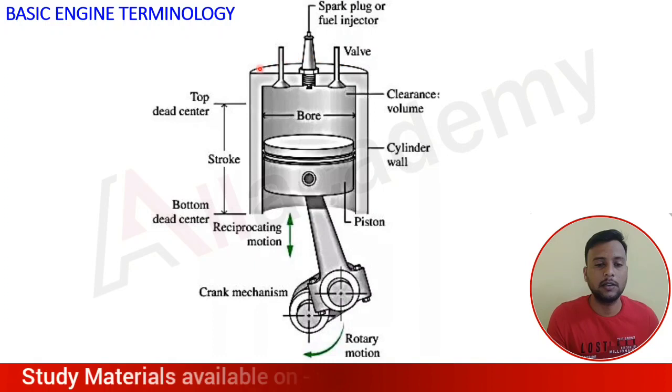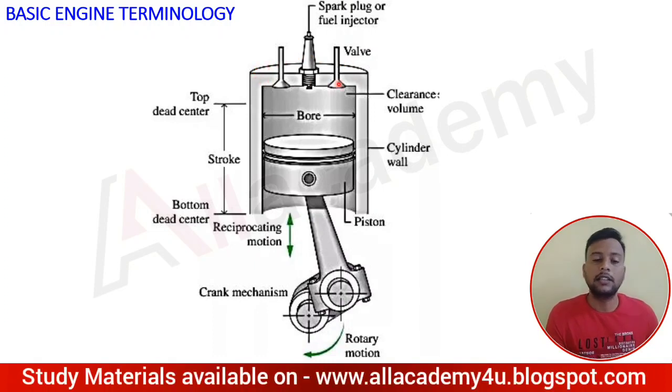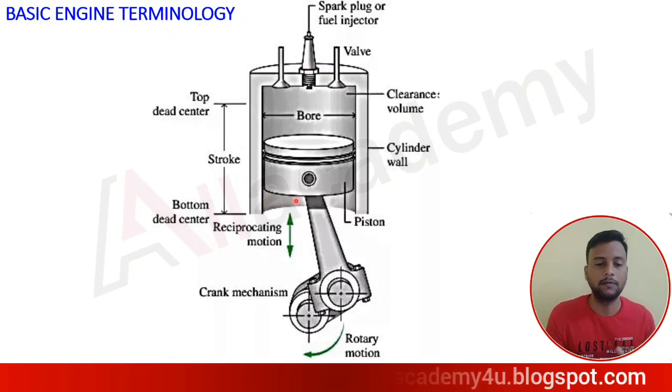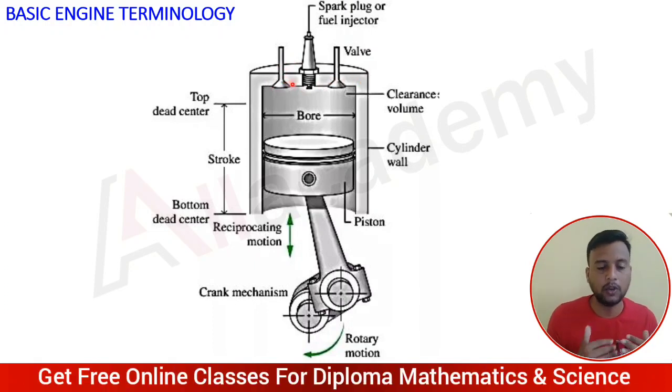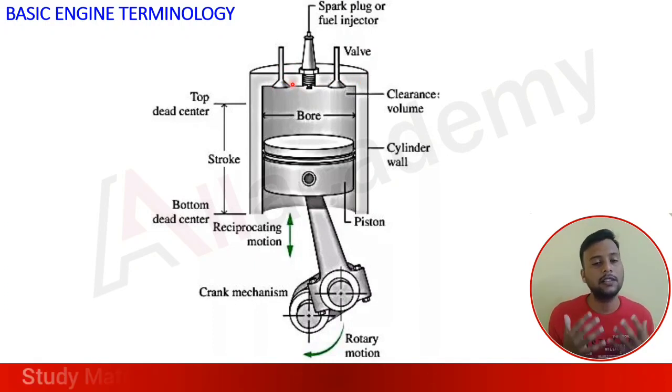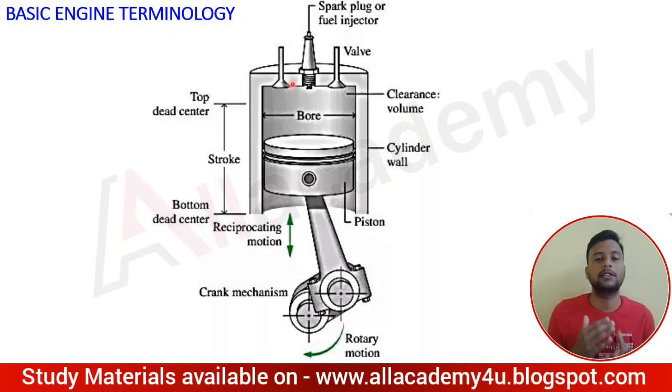Now coming to the next component, that is the cylinder head. This upper part is called the cylinder head. Again, all these components I am going to study in detail. What kind of material is used, what should be the strength, how the design should be, we will discuss in detail in this module 1. The cylinder head has to be very strong, because it has to withstand the pressure as well as the heat whenever combustion takes place inside the cylinder.